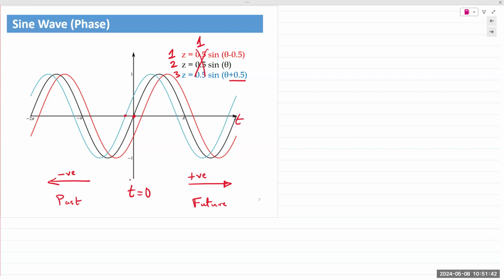Okay. It can also be described as the distance from time t equal to 0. So mathematically, that number, this distance from time t equal to 0, can be described as the phase. Okay. It's already ahead in time, so it's represented as a positive phase number. Yes. On the x-axis. X-axis is time, so it's describing this distance right there. It's the moment in time when it crosses the x-axis.